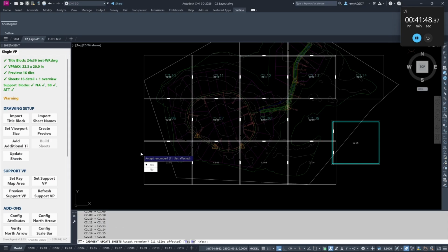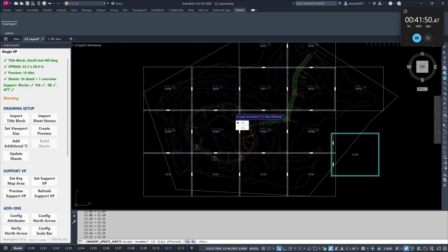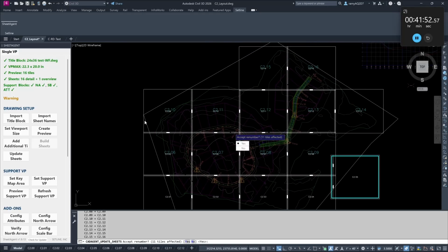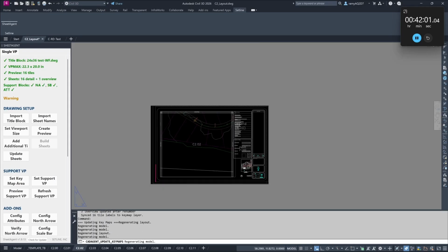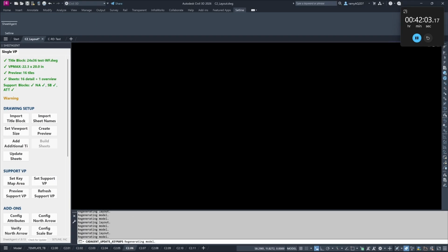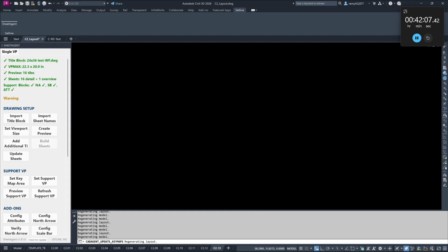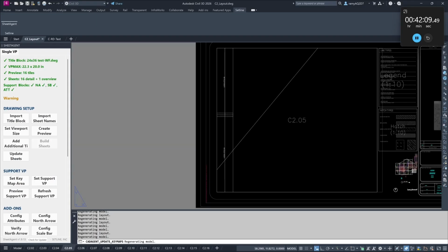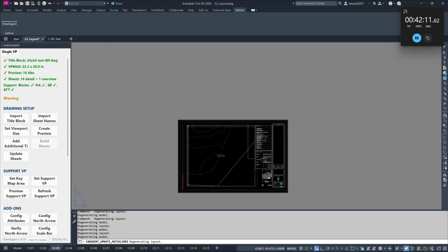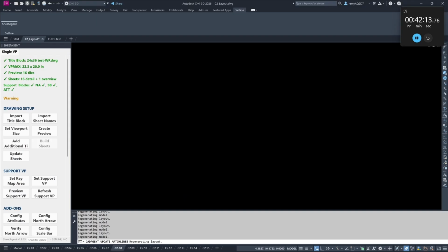So now we want to keep it. It's going to show you in cyan the renumbering of the remainder of the sheet. So 5 becomes 6, etc. until 15 becomes 16. Renumber, accept, yes. So we accepted. It's going to take a second. It's going to think, and it's going to start changing our layouts, changing our names. It's going to take a little bit, and it's going to eventually finish.